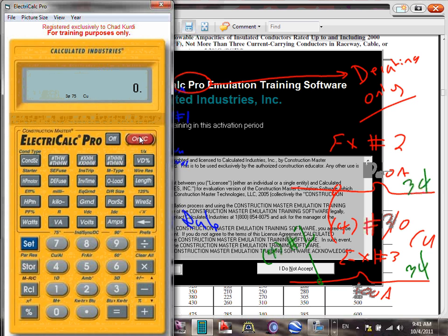I'm doing example number 2 with the calculator. I need 200 amp, regardless of the voltage. Hit the amp, so it identifies 200 amp, and hit the wire size, and off it goes with 3/0 copper. If you hit it one more time, it will tell you how many amps the 3/0 can carry. One more time, it will give you the kcmil for it. One more time, it'll tell you which table it came from. Isn't that cool? So you can review your work. That's very slick.